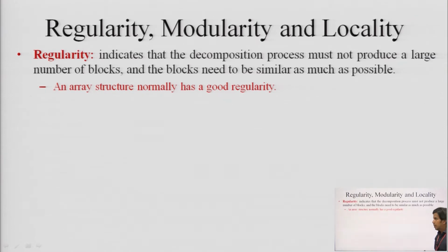Like, if I take the example of a 16-bit adder and split it into 4 different modules, meaning a 4-bit adder, a 4-bit adder, and so on, then we only have to design one 4-bit adder, and we can use the same module repeatedly. That shows the regularity.